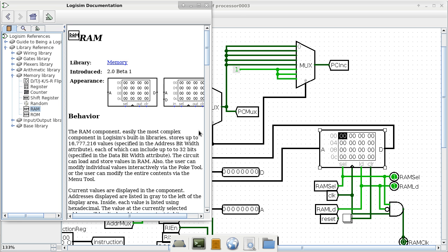But you can also read a location in RAM. It's like, oh, I want to go to that location in RAM and find out what is the content, what is the value stored at that location. So it's read-writable. Other than that, you can treat RAM as an array, okay? You have one way to control which location you want to access, which is through the A port, and then you also have another port that allows you to interact with the content at that location.